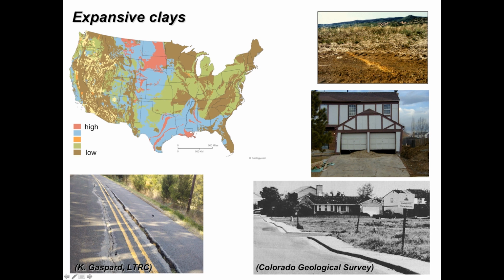You can imagine that when we put an impervious barrier over clay, really what happens is the underlying soil wets up with time, and so we have relatively constant moisture condition under the center line of this pavement, but near the edges that are exposed to the atmosphere, that soil experiences fluctuations, wetting and drying.